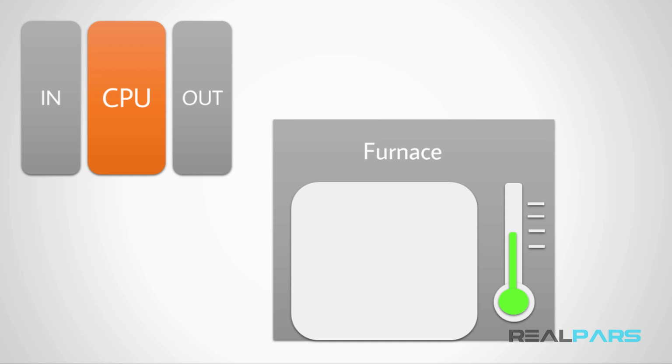The first step to control the furnace's temperature is having a facility that measures the furnace's temperature for us, which tells us the furnace's temperature at any point in time. In order to measure the furnace's temperature, we can use a thermocouple. A thermocouple is a type of heat sensor that can measure the temperature for us in a certain range.